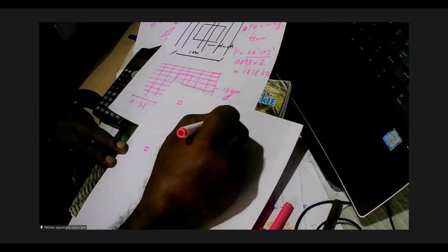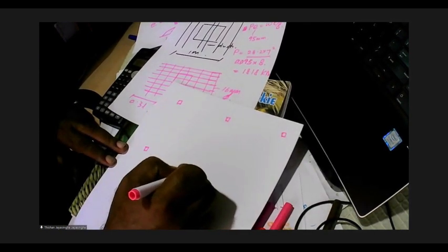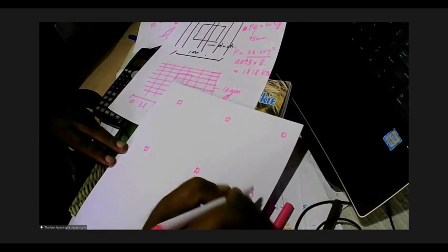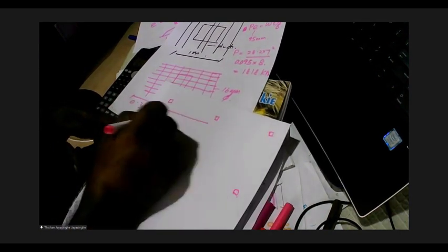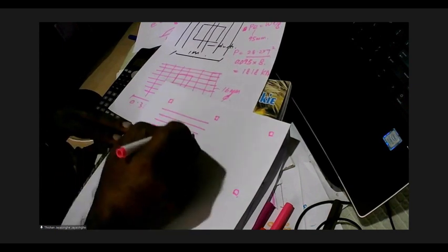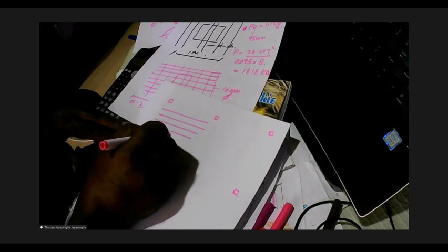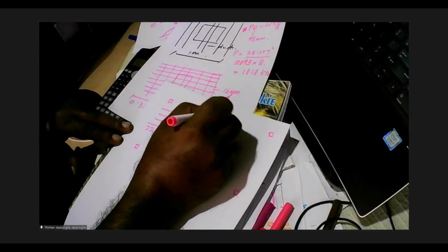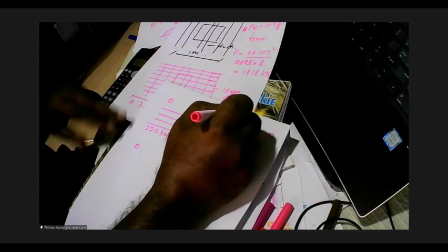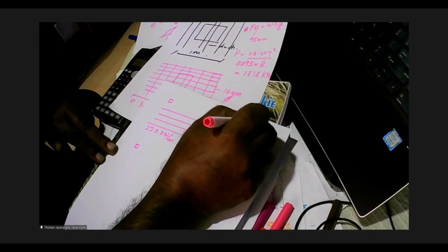But these are little approximate calculations because there can be few variations here and there. So this way, we know pre-stress force is 220 kilonewtons per meter. And over this width, we need a lot of pre-stress, and we need 1880 kilonewtons per meter.